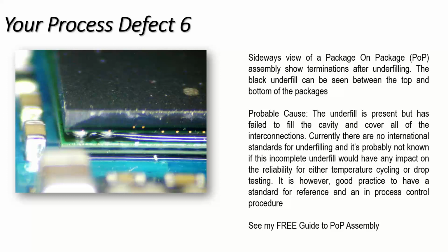So you've got a microprocessor and a memory device soldered together, which is mounted on a board, and we're soldering it all in one operation. But this is an example of underfill and exposed balls. What you're looking at here is 2 balls which are not completely underfilled.